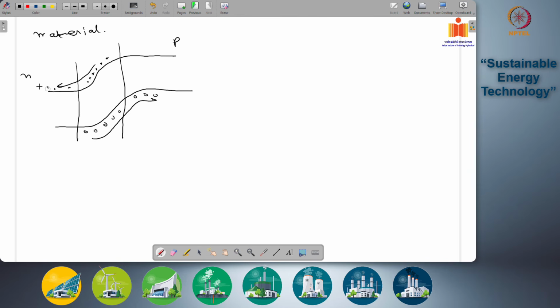Now once these electrons are here and these holes are here, there is no further potential gradient to move these electrons and holes further. So they may spend a lot of time in this region with a flat potential gradient and recombine with any electrons that are available at the top surface here. So there can be further recombination losses if these holes and electrons are not driven further down to these places. You can have a case that the electron will move down here or the hole will move up here because it gains excess energy through some process.